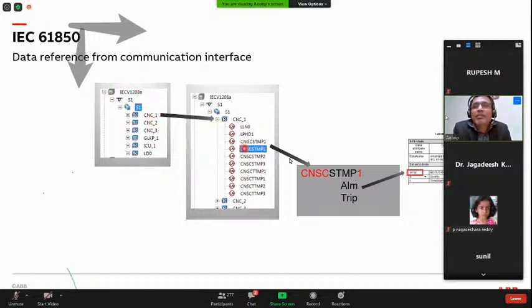Now you can see that this is what we have designed before. So in one of the logical devices, the function which we designed in the previous slides is here. So it's a conductor temperature, and you have similar kinds of many functionalities here. As I mentioned, a logical device has many logical nodes inside it. Logical nodes means it's a specific function inside your substation automation.